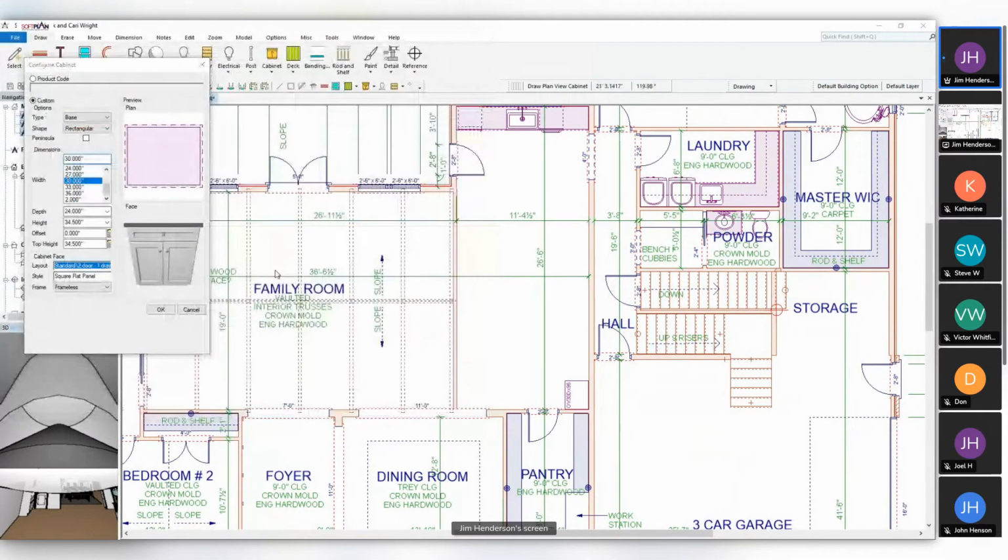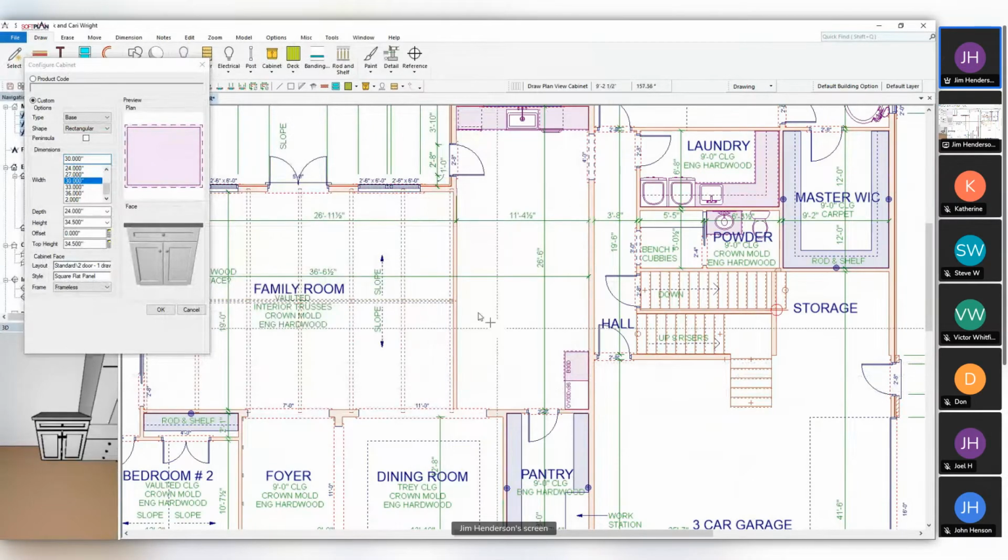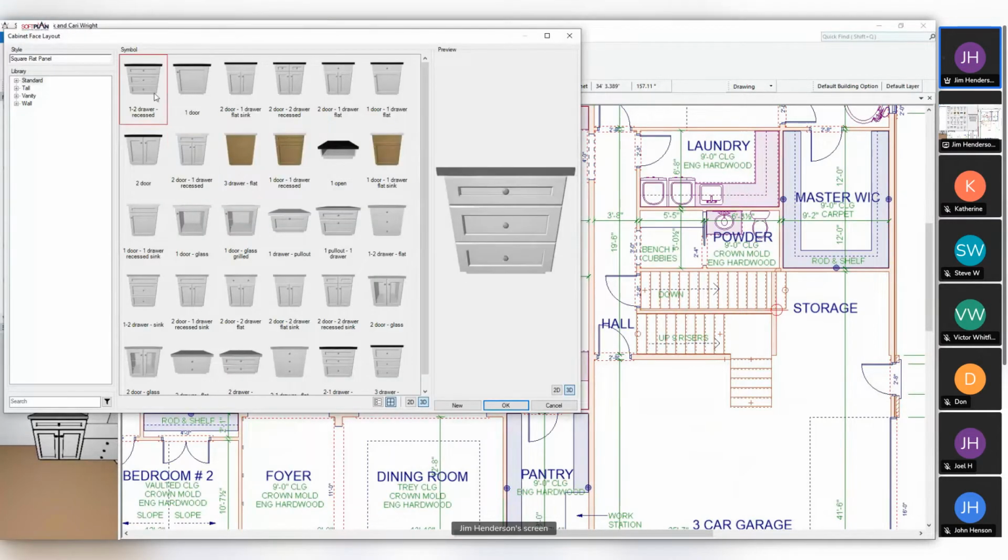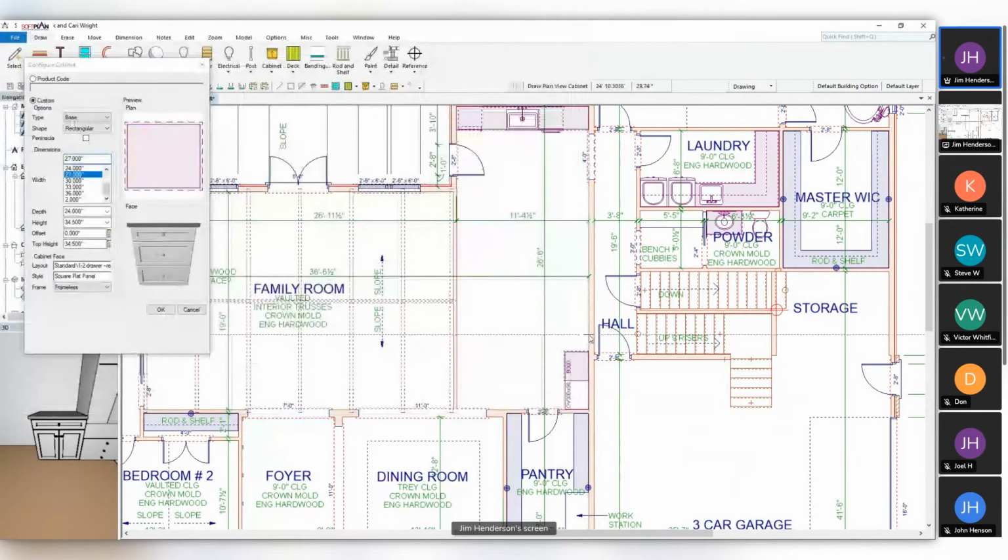And so I'm drawing a 30-inch cabinet beside the oven door. Then I can return here and select, let's say, the 27-inch, and I'm going to add in drawers only. By leaving the dialog open, I can change that on the fly. Now, as I said, there's somewhat where I know the design, right?